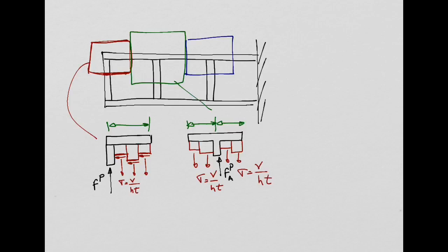So what I'm going to assume here, and it is a reasonable assumption, is, look, what you have here in red, this is because of the development of the diagonal tension field, right? Yeah? So when the web buckles, this direct stress sigma is developed and is going to be transferred to the posts as well. Not only to the flanges, but also to the posts. And then what I'm going to say is that if I look at this web here, maybe I can shade this web like this.